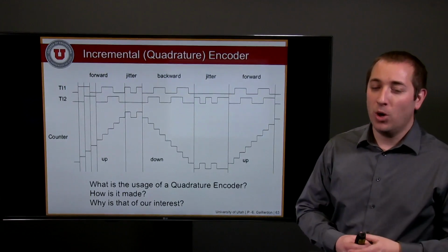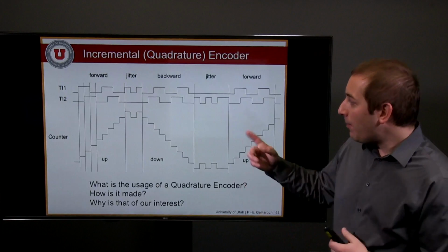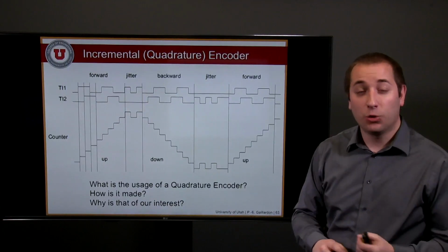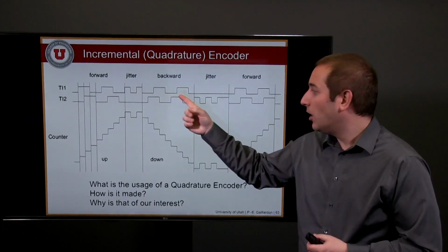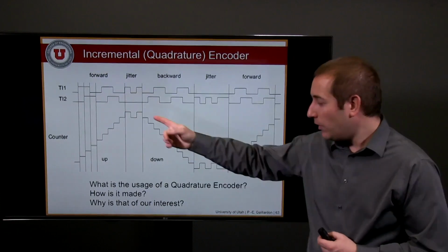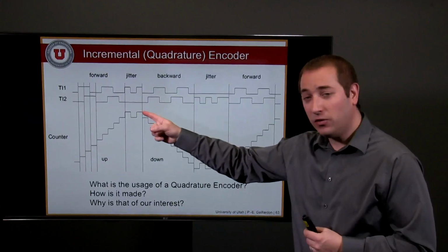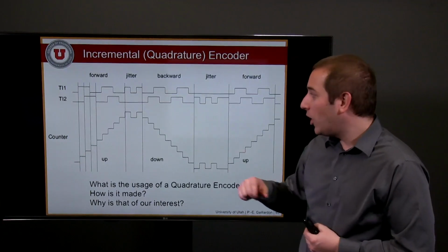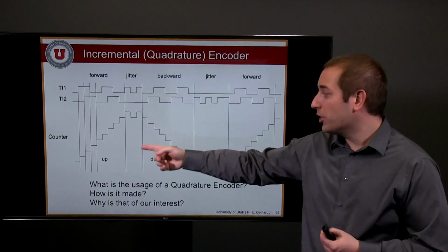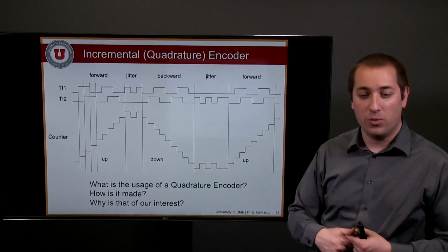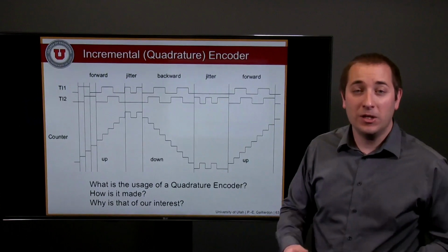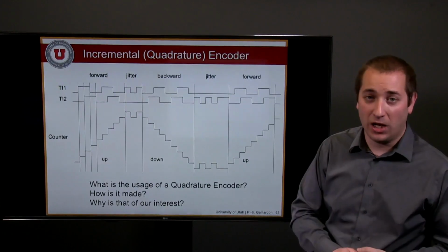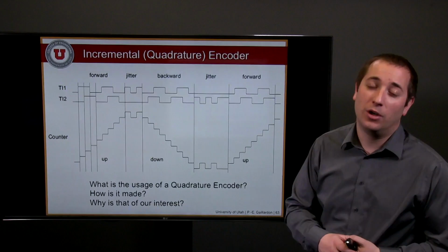The incremental and Quadrature encoder mode are actually fairly interesting. What happens in that case is that you have external signals that have a 90-degree phase difference, and your Quadrature encoder will look for not only the different ticks, but also the phase advance or phase delay. As such, that will trigger your counter to increment up or down depending on the value. What is that used for? It is fundamental to monitor the rotation speed of a motor as well as the direction at the same time. And we're going to use that heavily in our DC motor project.